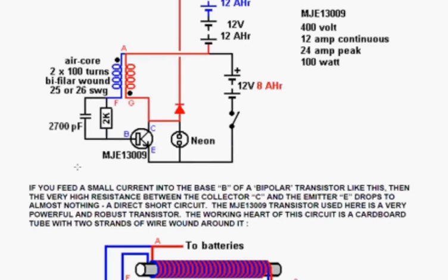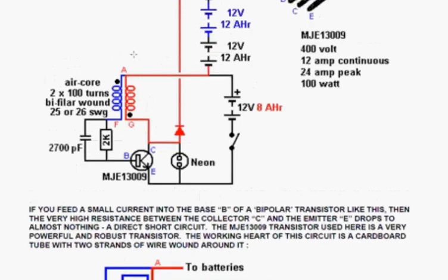The diode can be any diode you want. Personally, I would recommend a UF5408, which is 1,000 volts, 3 amps, and very fast acting. But I imagine that Alex just used a 1N4007, which only costs 3p. A diode of 3p is not a problem.